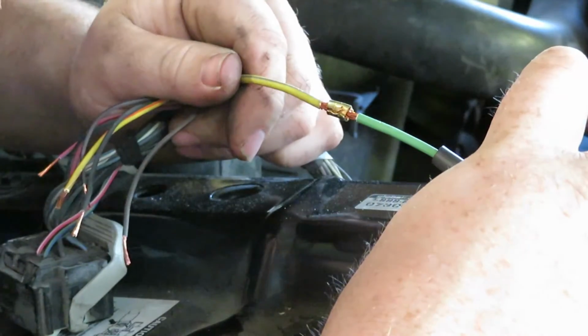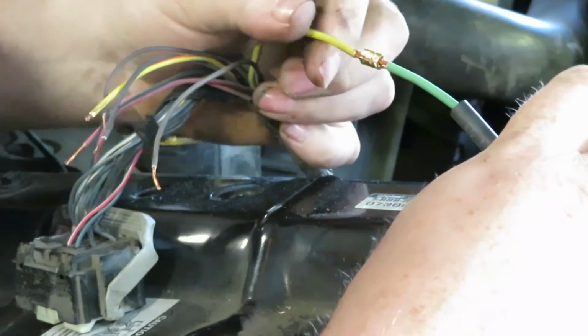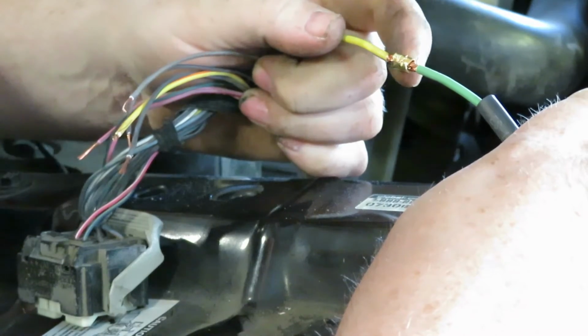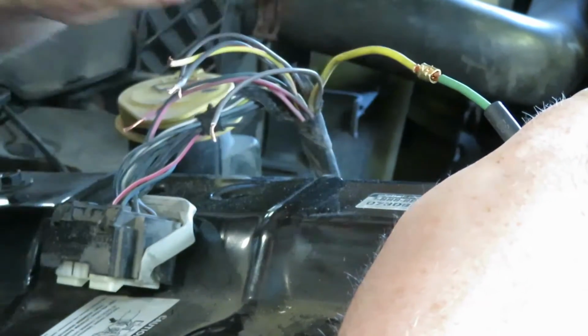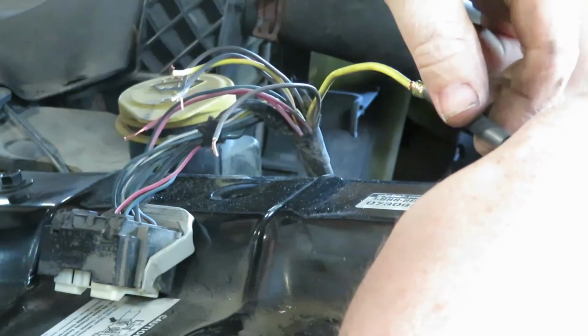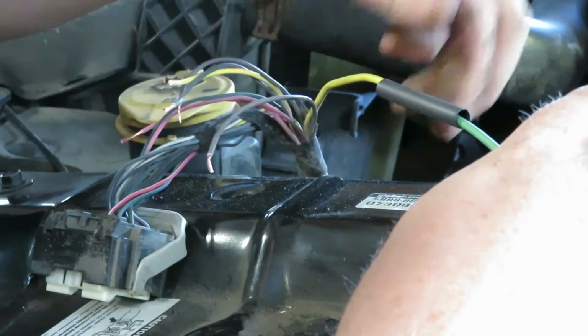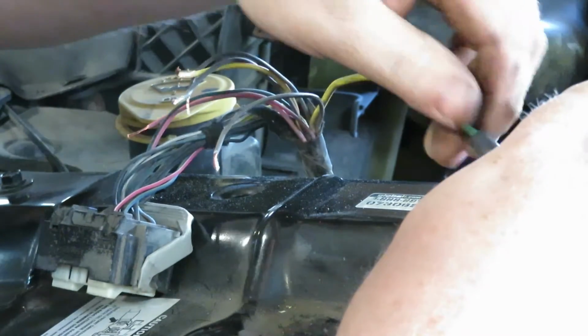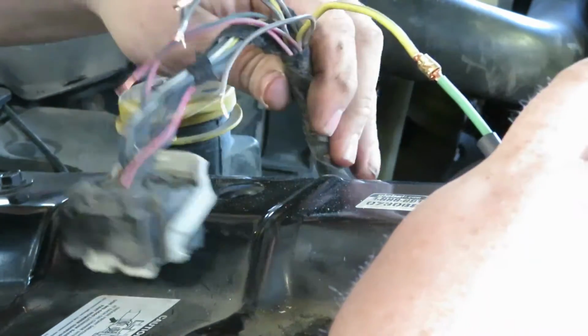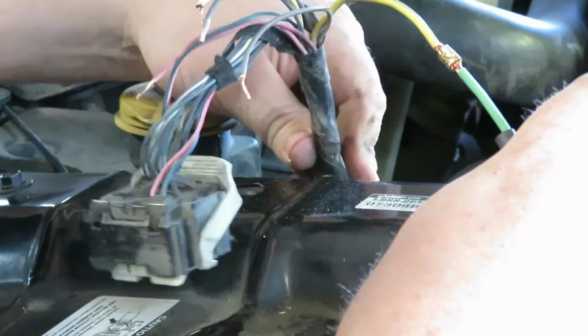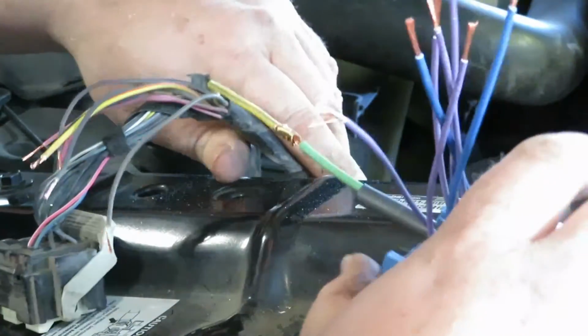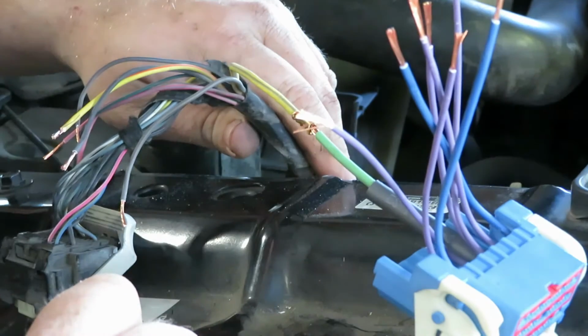So then you have a connection that looks like this. So there's still enough wire exposed that when you heat it up and get the solder in there, all the solder will leach into it, and it's small enough around for the shrink tube to fit over. So I'm going to get something to clamp this up here like that, and we'll get to soldering.